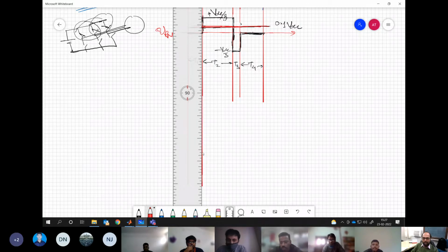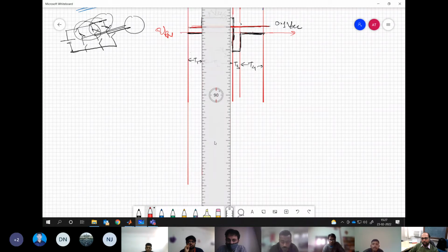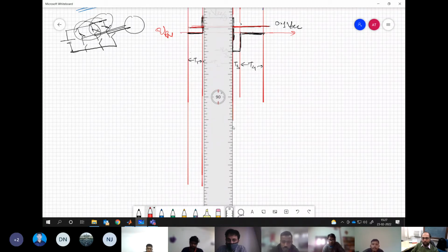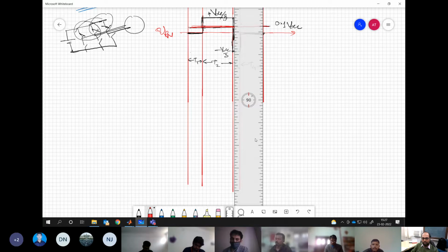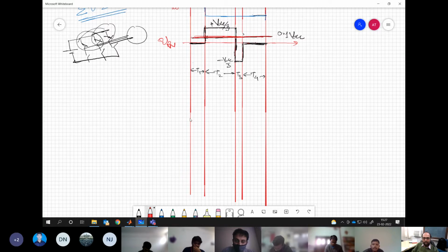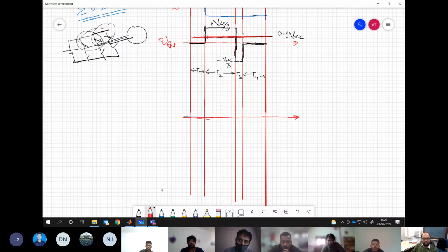That much error we are creating on the system. That much error voltage we are feeding, which is not necessary to feed. But what to do? We cannot help that. It is going because of the PWM action. So let us write the error voltage. Now, what is the error voltage during interval T1? Minus 0.1 VDC, say somewhere here.